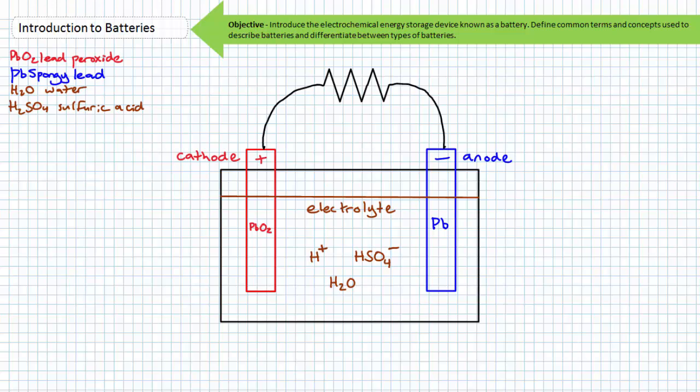The concentration of the acid-water electrolyte mixture is a direct means of ascertaining a given battery's state of charge, although not exactly the most convenient means of doing so. We'll discuss specific gravity measurements using a hydrometer and alternate means of measuring state of charge in a moment. Before we delve deeper into this analysis, I must remind you that conventional current flows from the positive terminal of an active source to the negative terminal.